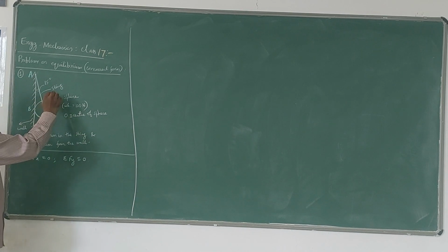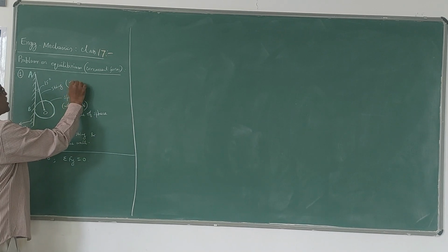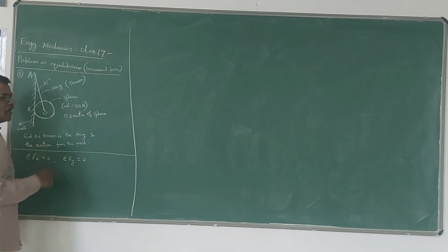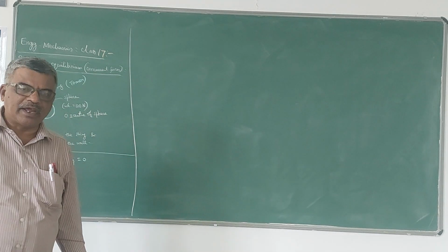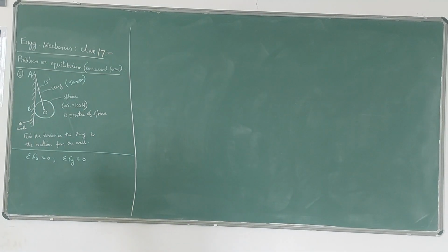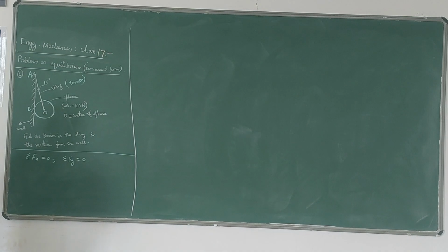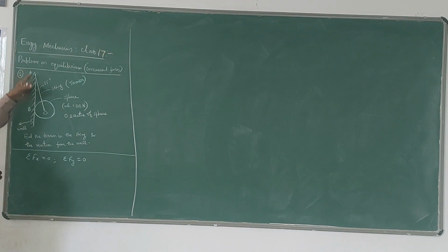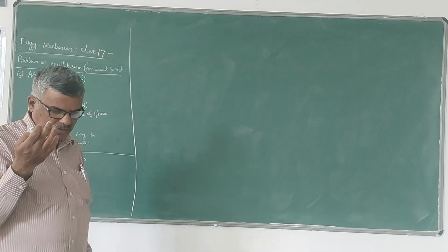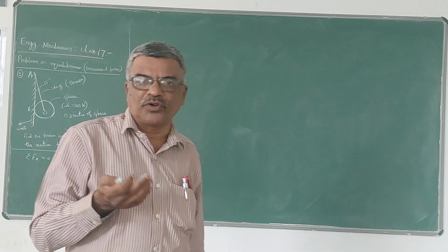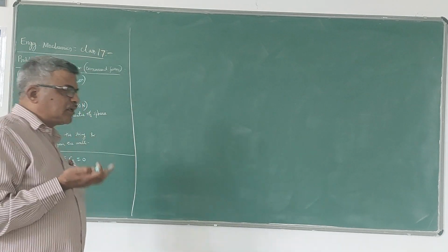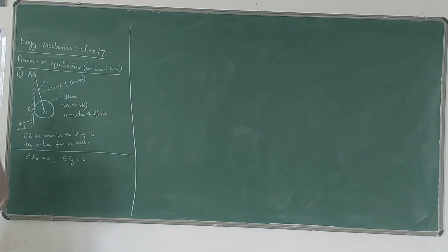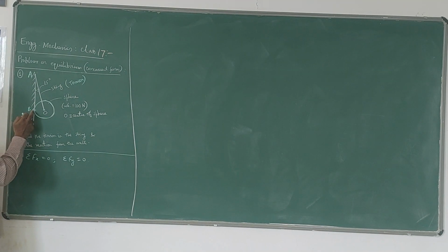So, the purpose of providing a string is to carry tension force. So, always the force in a string will be a tension force. It can be a cable or a string. So, tension force will be there in this string, and there will be a reaction at this contact point. So, I have told that to withstand the forces or actions, they should develop reactions. So that reaction will be developed at B, where the sphere is touching this wall.